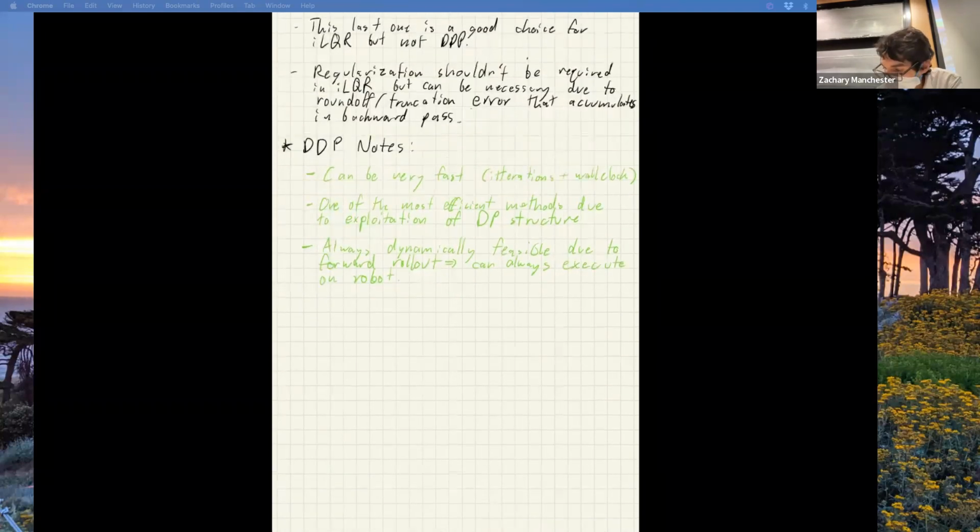Okay, another cool thing about this that we mentioned in passing, but I haven't really dug into and didn't do any examples yet, is that you get a TV LQR tracking controller for free. So we talked about how the backward pass of LQR and DDP, the Ks you're getting there, and most of that backward pass is the same exact Riccati equation as LQR.